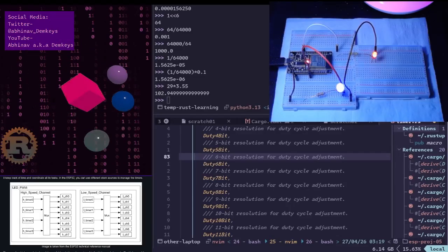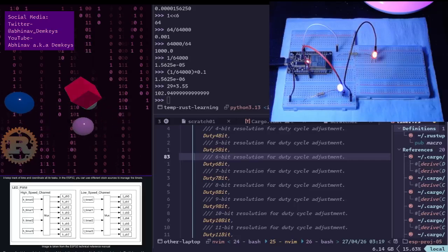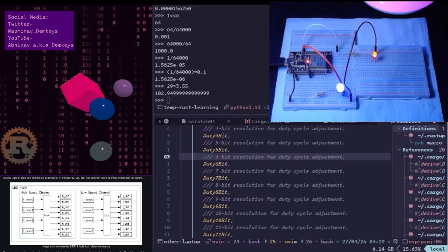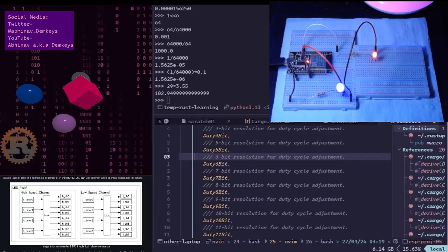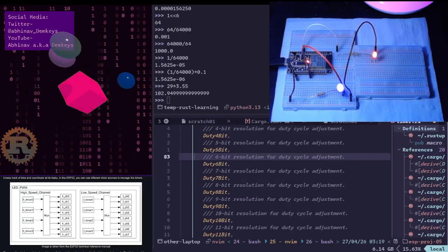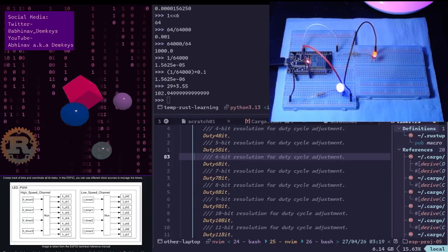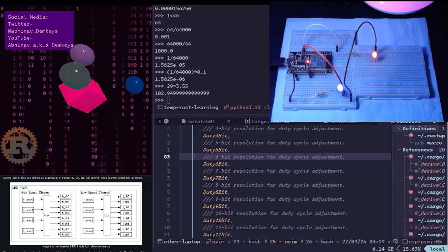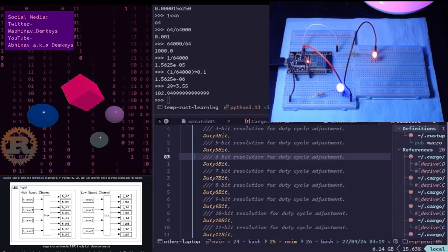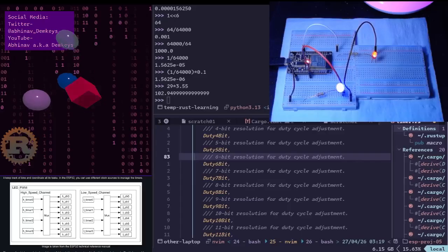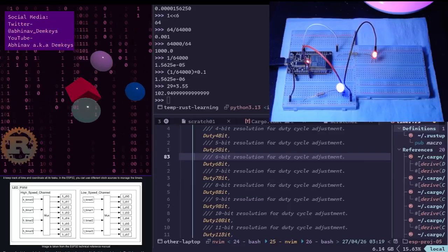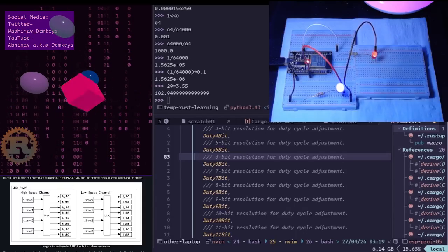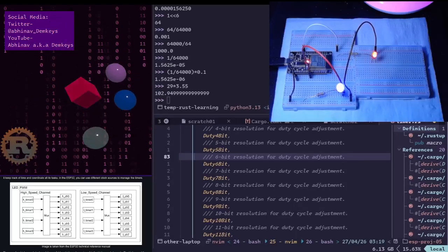And I did a bunch of research on it. I even found out about a Rust crate that adds support for CH32 microcontrollers, and it specifically also has support for the V003 line of CH32 microcontrollers. You do, however, need a programmer. What do you even call those devices? They're like debugging devices, JTAG slash debugger device.